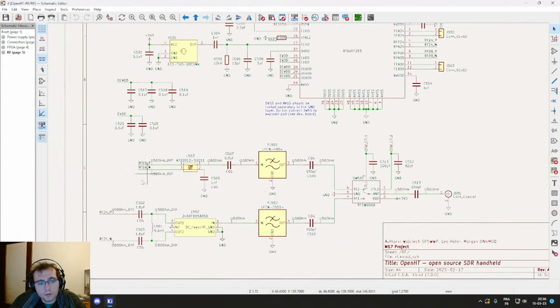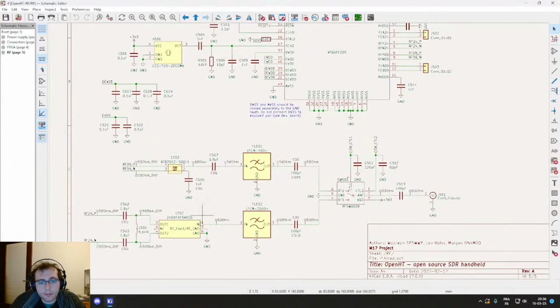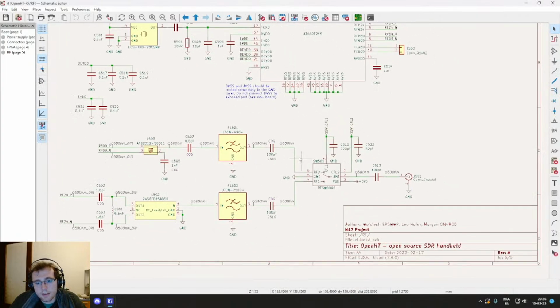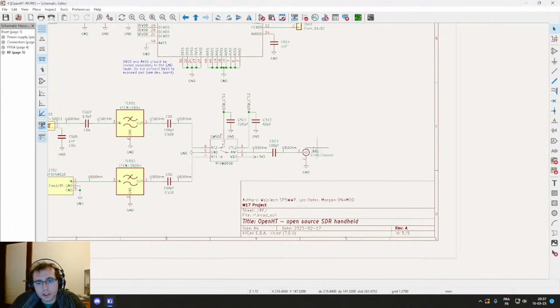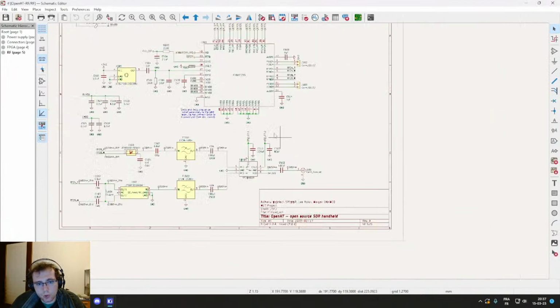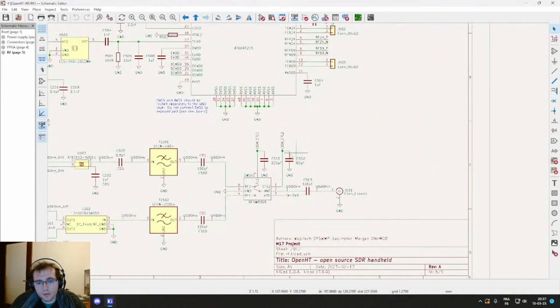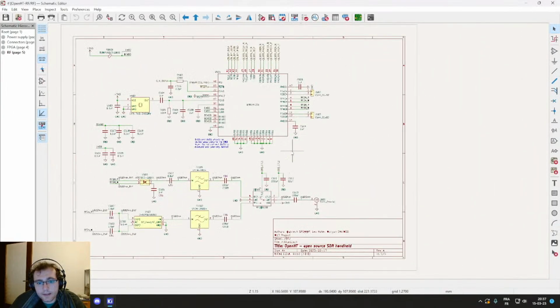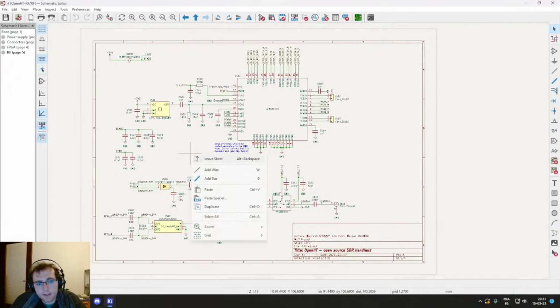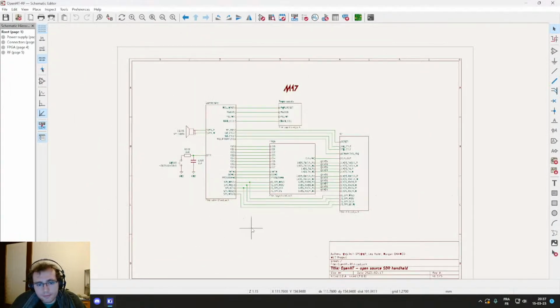And so the RF tracks are going to go through a balun because it's a differential output, but we need single-ended signals. Then some filter, a switch, and then one antenna. So that's as easy as we can make it. We have no power amplifier yet, because we have to keep the design simple if we want to make some progress, of course.